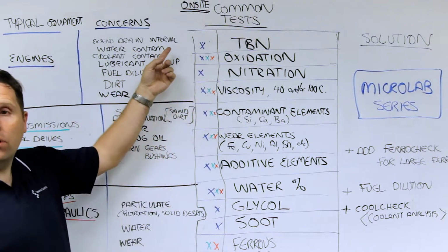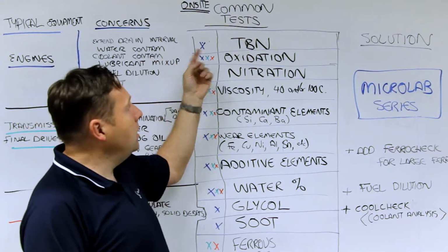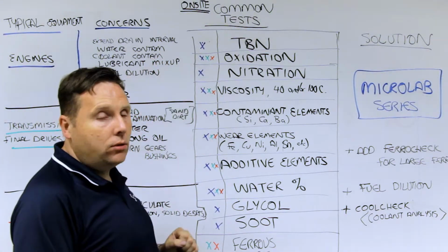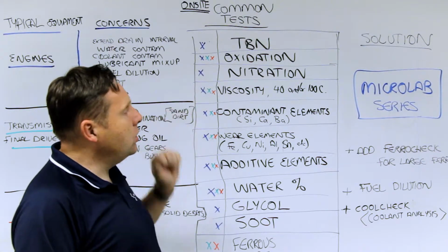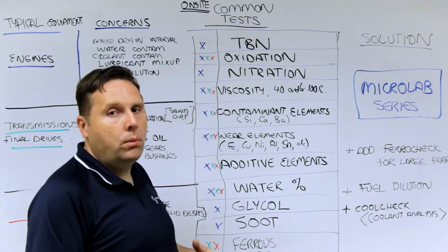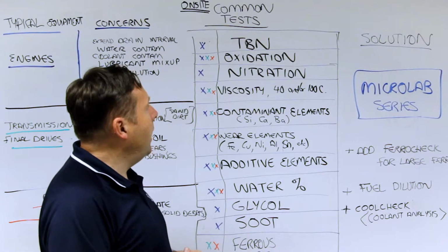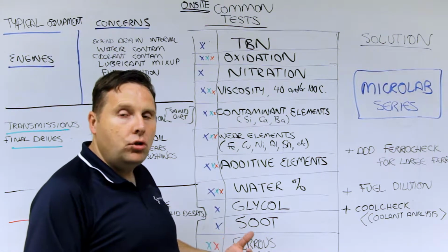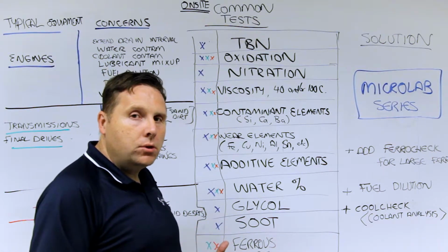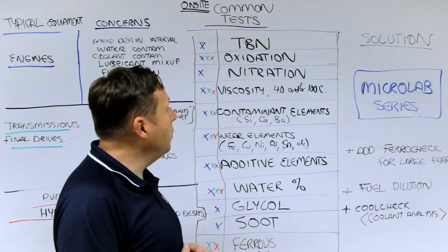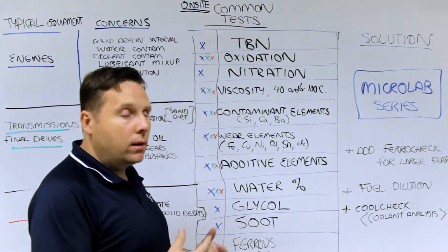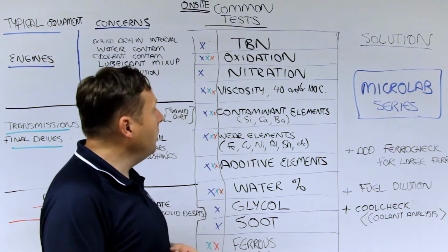That's an indication for the level of oil change in the end, for extending drain interval. We look at oxidation and nitration, of course, to determine the engine performance. If we've got excessive nitration, we know that there can be problems with the turbo. We know that the engine's not running properly. Oxidation, if the oil is already being harshly or overheating.